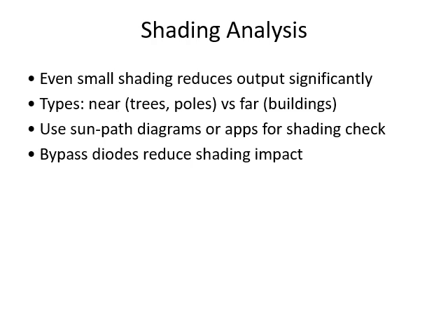It normally works as reverse biased. That means as long as the photovoltaic cells are getting enough light, it won't do anything. It will just do nothing. But when shading occurs, the bypass diode becomes forward biased, allowing the current to bypass the shaded cell group.